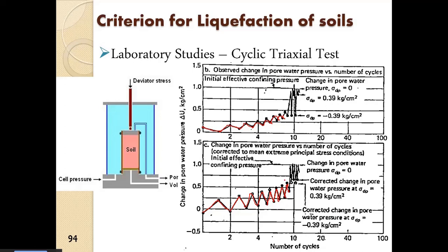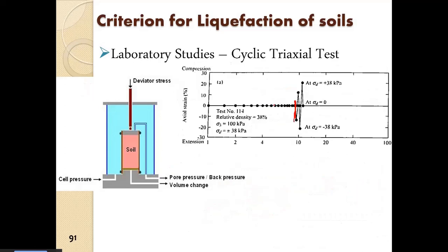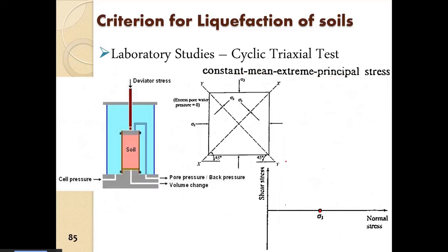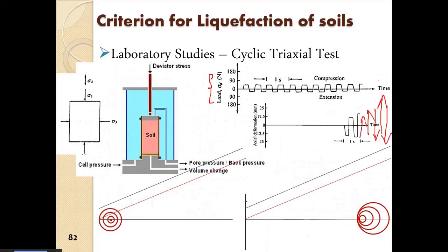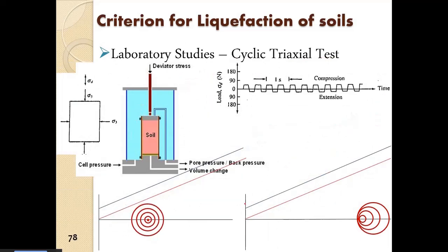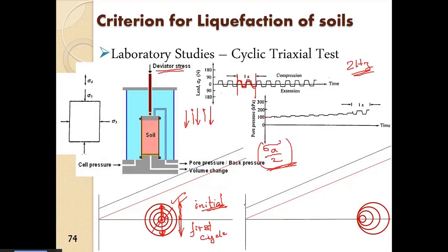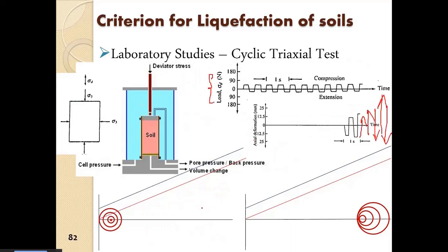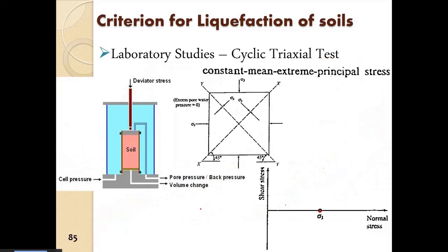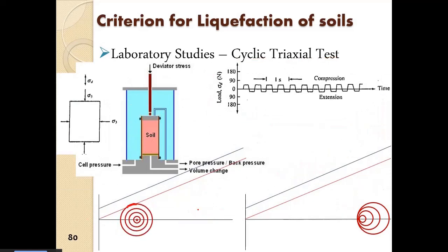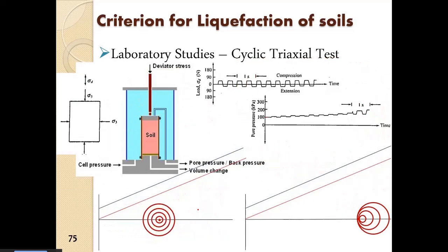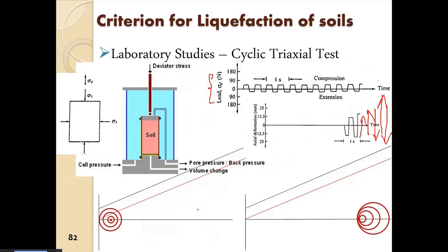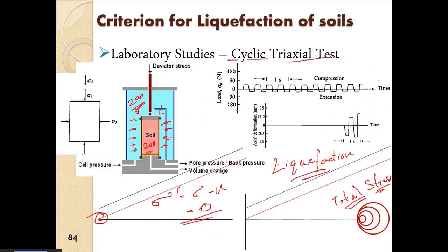As I have explained in the previous case, the increment in the pore pressure actually helps us keep the stress condition equivalent to the in situ condition, right? So that is one advantage. Here you see with increment in pore pressure, ultimately we have liquefaction. It will move like this, total stress remaining the same.